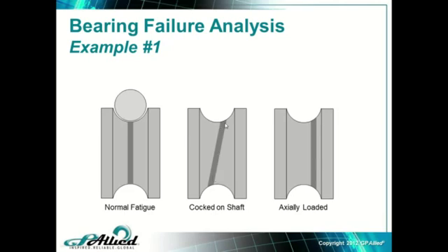If we allow it to spall, then what happens is I'll get spalling all the way around the race, all the way through here, and I will lose that pattern. I'll lose my evidence. So there is a very big business case to identifying these defects high up on the P2F curve and then getting them out before they're hot to the touch, before you can hear them from the parking lot. Because if I can get them out in time and I can cut them apart and spend 5 minutes looking at it and spend 5 minutes reviewing it with my crew, there can be a lot of learning going on, because we can figure out who's got the skill set and knowledge, who doesn't have the skill set and knowledge, and who just was kind of in a hurry.